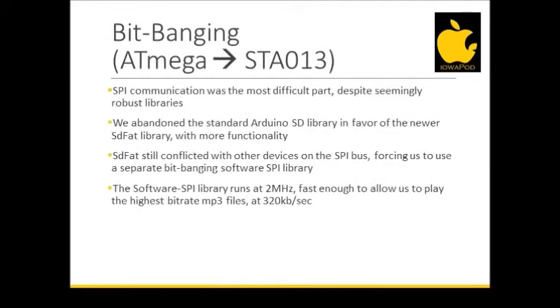As it turns out, the seemingly robust libraries for communication that initially attracted us to using the Arduino IDE as the base of our project caused a lot of frustration. The SD library that Arduino had for interacting with a file system on an SD card seemed at first to work really well, but upon looking at it further, we found that it seemed to use the SPI bus in a fashion that prevented the SPI library from functioning with anything else at all.